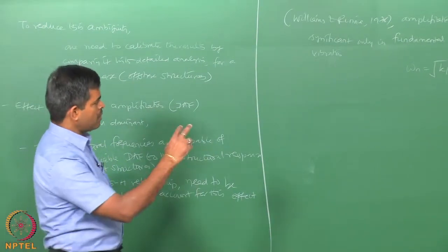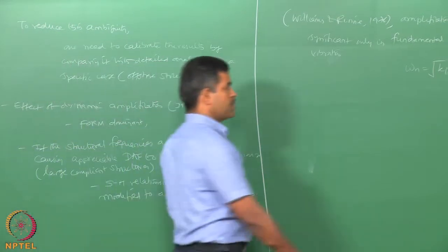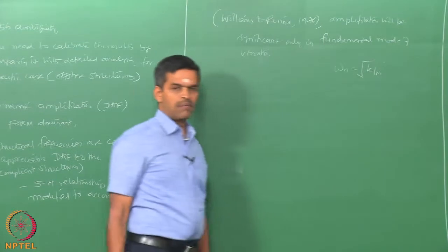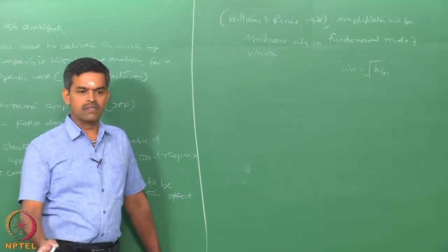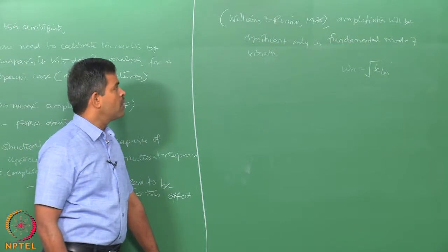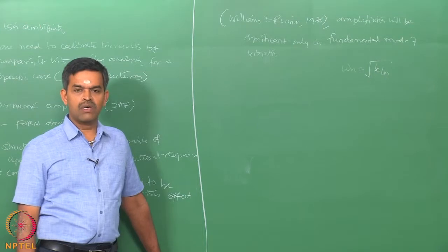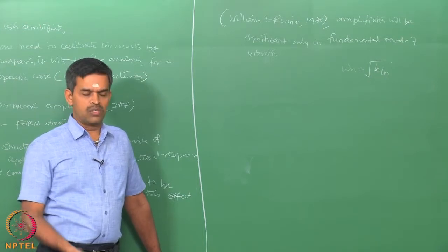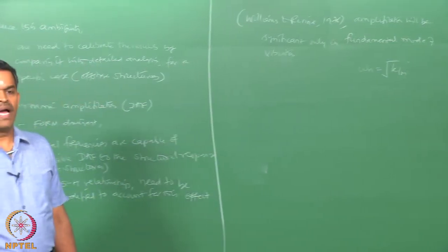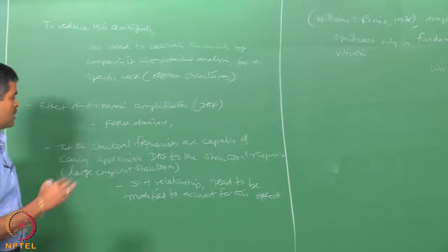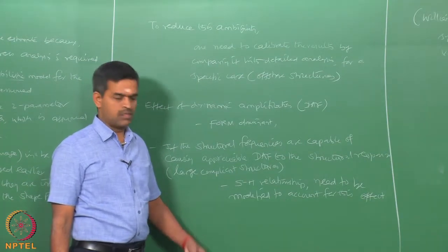So that the fundamental mode of vibration, depending upon the modal participation of the first mode, can be designed in such a manner that they will not land up in large amplification factors, because if the design includes a very large amplification factor, then that may add up to the fatigue damage which will be caused by the cyclic load effects on the system.